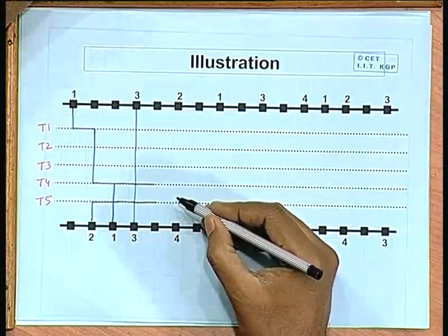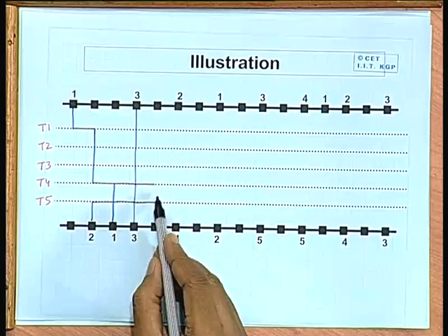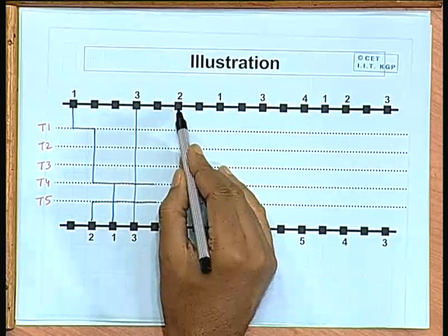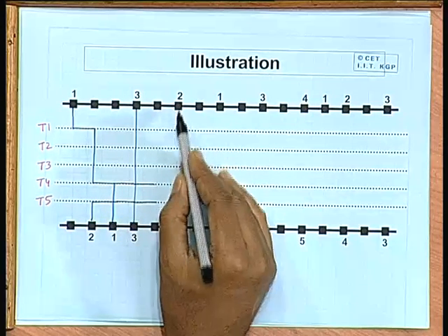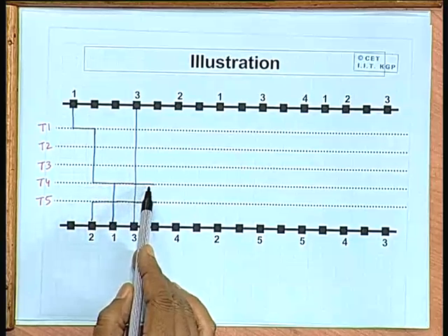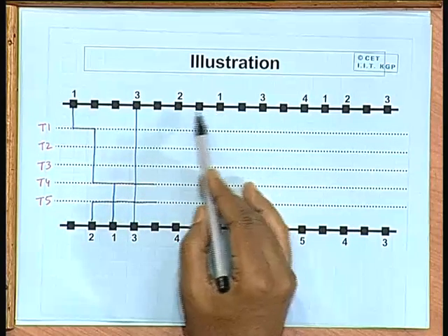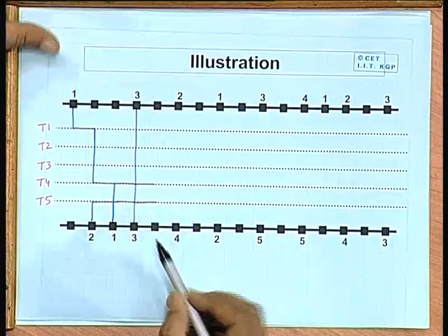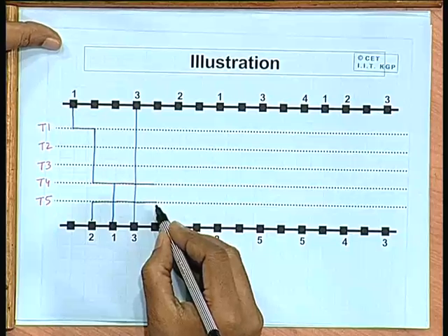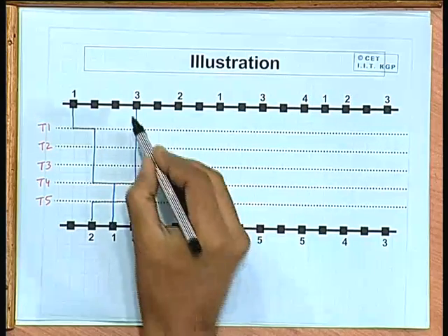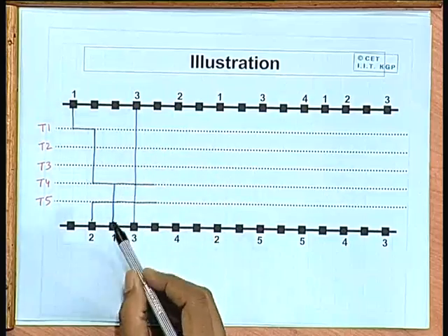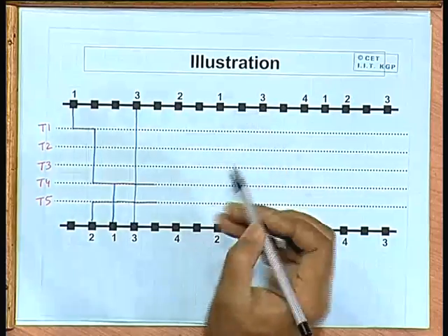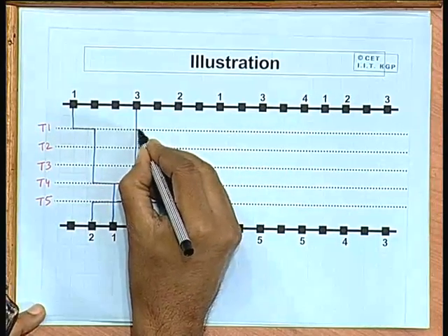Now, you have a choice out here. See, this is the net for 2, the next terminal for net 2 is here, and this is 1, and 1 is also top, but 1 is later. So 2 comes first. So 2 will be given priority. So net number 2 will make a, okay, sorry, I missed one point. This 3, although you have connected, there is another 3 terminal on the right, and that is towards the top. So you also start a segment from here like this.